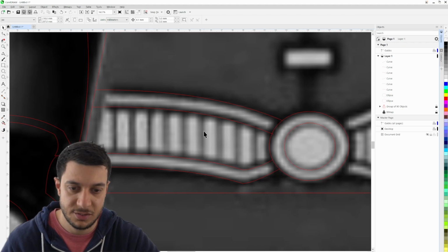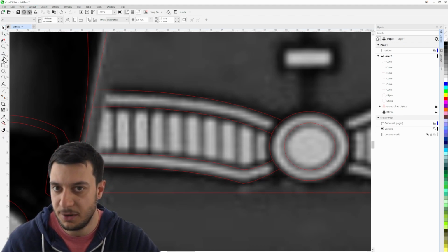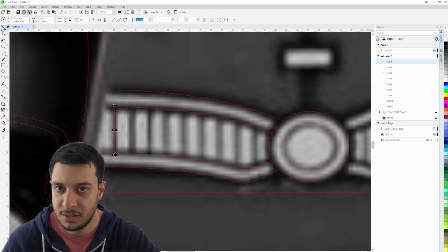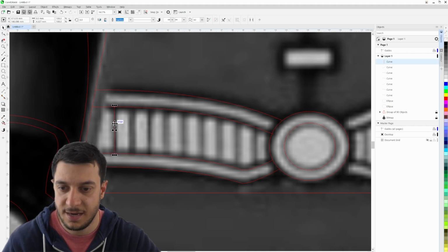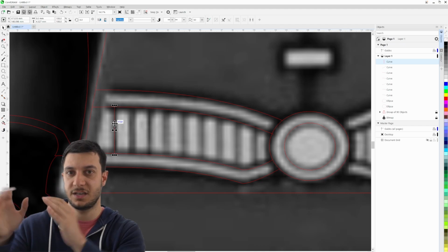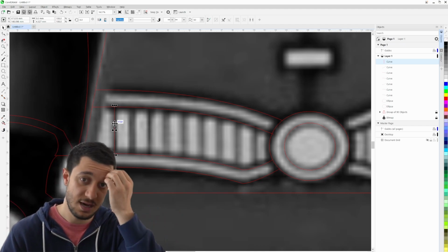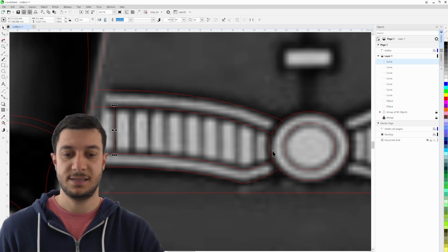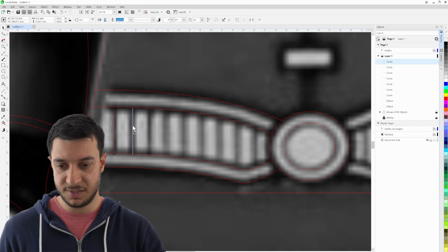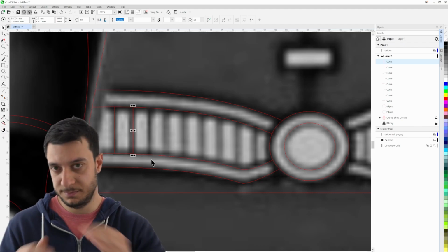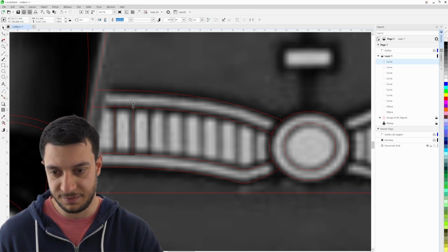Now to make these lines in his belt, I would probably use the 2-point line tool, click and pull down, and then you can grab that line. And because we started on the left hand side, you can see it's much taller than the lines on the right. So when we pull this across, it should be able to reach the top and the bottom line. So, you know, we can just cut off the excess.